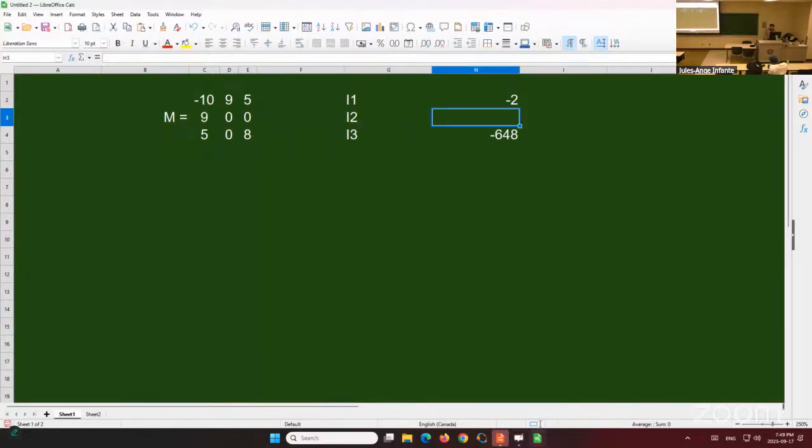And our second stress invariant will be the determinant of this plus, or we can do it manually if we prefer. This times this minus this times that. We'll write them as separate values and then we'll add them together, okay? And then we have the determinant of this times that minus this times that, right?